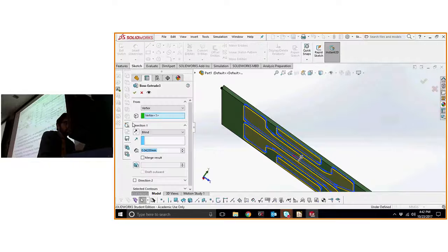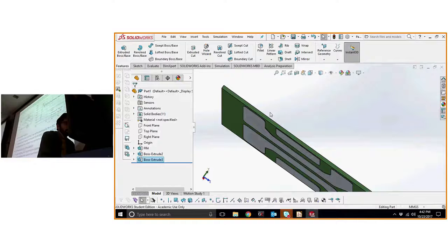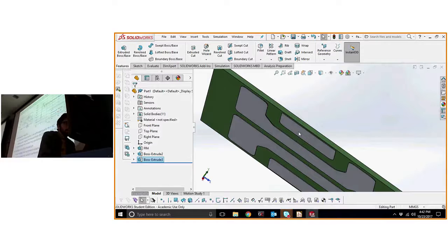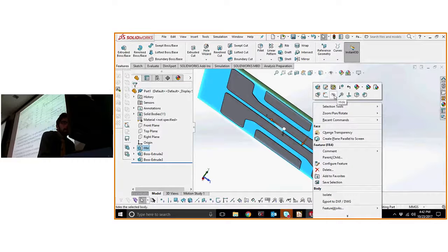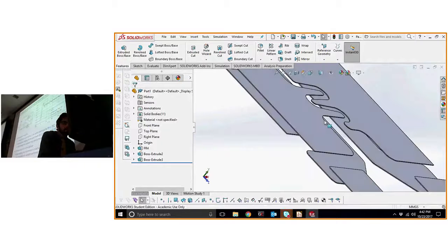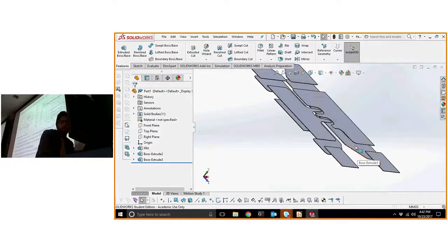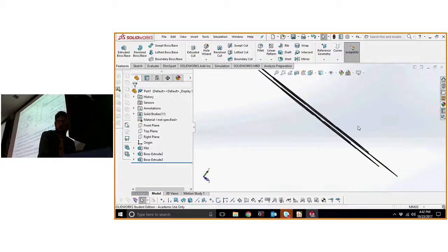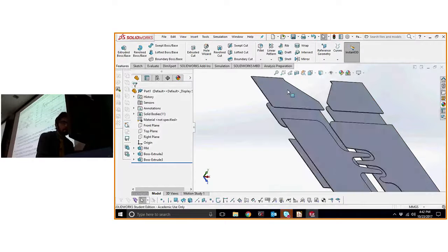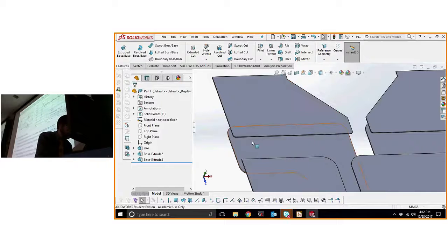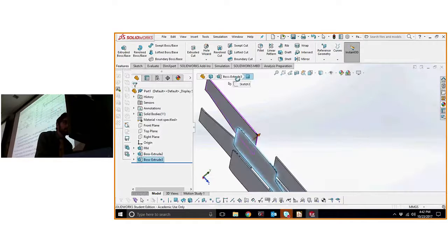Yeah, we have to change the extrude direction so that it's down. Yeah, top, bottom. At this point, I just want to work on the electrical connections. So I'm going to hide the PCB. And instead of putting a whole bunch of vias in, especially when the vias are like 10 mil diameter or really small, that's going to be complicated for Q3D to mesh over later on. So for this study, I did a really simple way of connecting them.